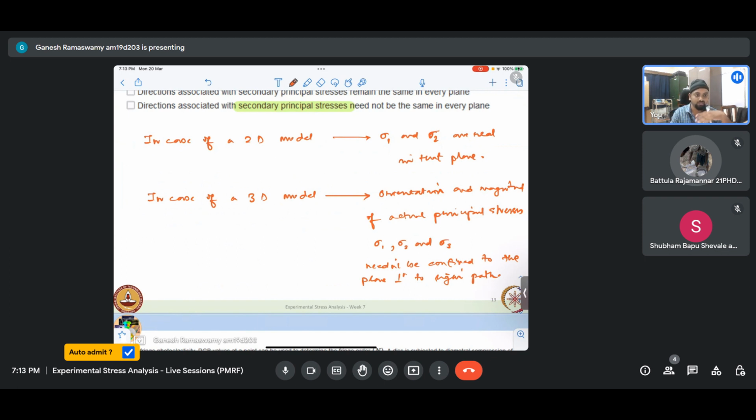So once we have this at every plane and we stitch it together, we can get the entire three-dimensional stress field. That is meaningful. But for one plane, it is not right to say that the principal stresses at that point in that plane are in that direction, because the orientation could be arbitrary and we are only seeing the 2D projections of those stresses in the plane which we have sliced. So I hope that that is clear.